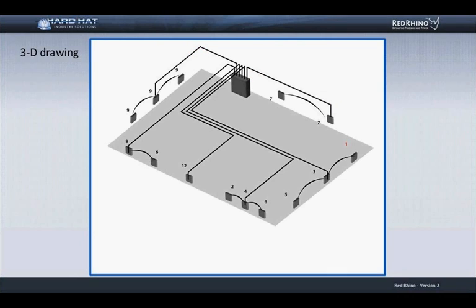Next, we will need to consider wire makeup for branch circuits takeoff. Wire makeup is the length of wire needed to extend past the end of the conduit to the termination point. Wire makeup must be included to capture the wire cost. In this case, at the electrical panel, the wire would extend past the end of the conduit and terminate on the circuit breakers.